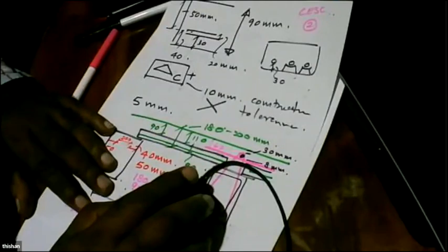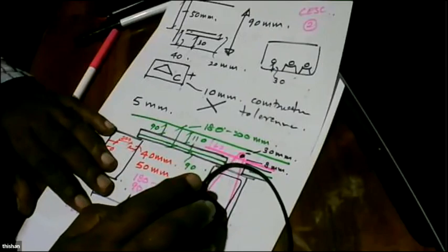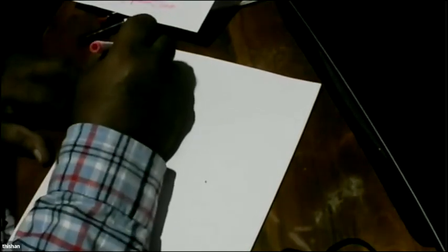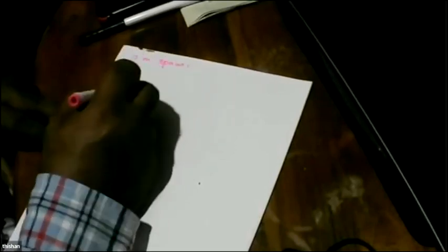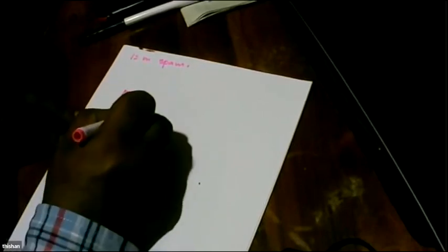So the guideline is, now let's say we are going for a 12-meter span. That is a 40 feet bridge. Not a small bridge. And the size of the beam will be 650 by 300. The guideline given is 650 by 300.